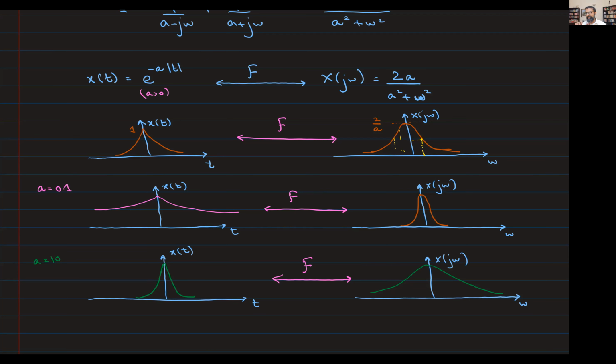What you're saying is you take the Fourier transform and just amplify some of the frequency content more than the others. Yes sir, makes sense. So vocals are at lower frequencies, or bass or the drums are at even lower frequencies. If you want to amplify the drums, you just amplify the low frequency components compared to the high frequency components, and that's equalization. The basic tool is the Fourier transform.